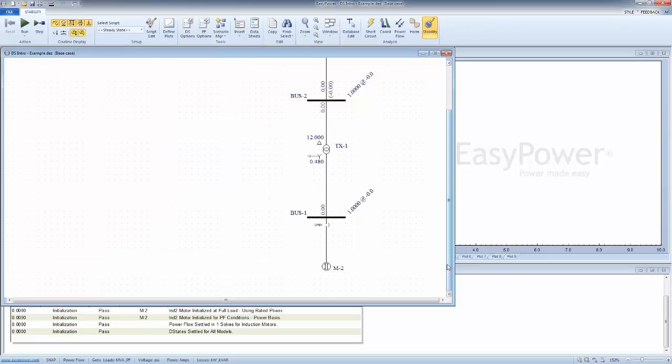So this is basically the point I'm trying to make: this is your load flow module with a lot more features to offer. Right now I just ran it for load flow because maybe I was in a hurry, or maybe you just wanted to see how it looks if the motor is offline. But let's not forget that at any moment I can double click on this guy and run a short circuit and see the waveforms. I can do that anytime. If I decide to run a script or define a script, I can go define a script and run it.